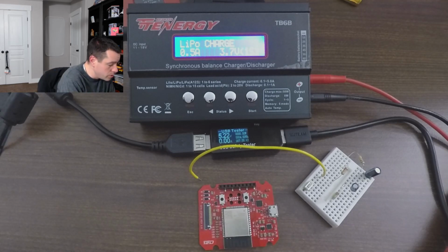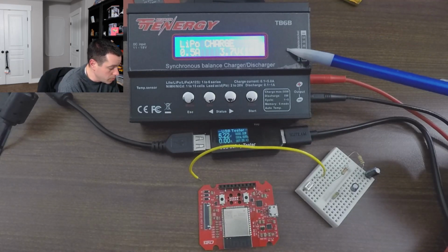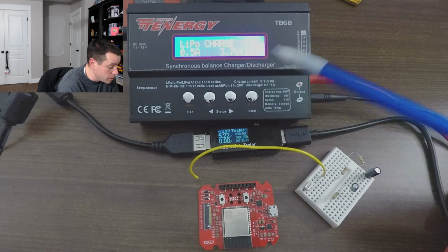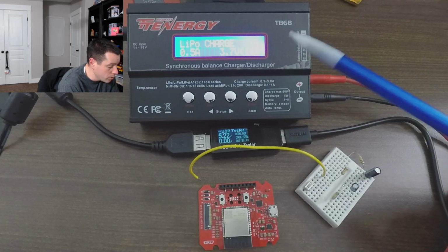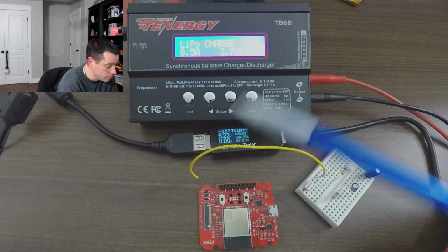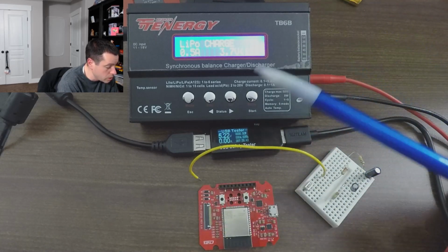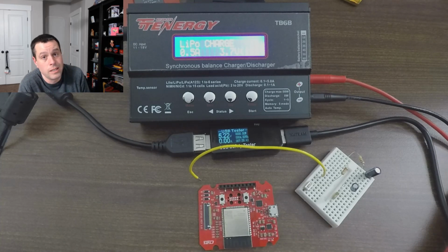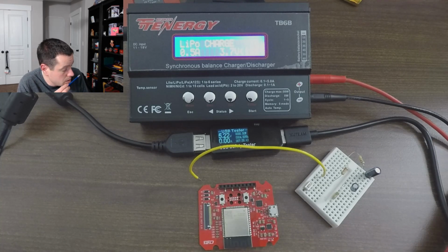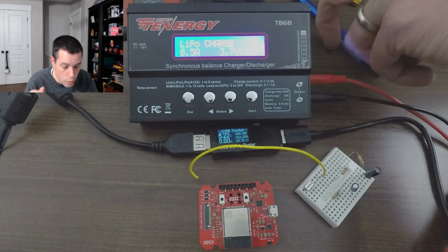But anyway, I can use this to put a battery in different voltages very quickly. I can put one at 4.2 volts, one at 4.1, one at 4, 3.9, 3.7, 3.8, 3.87654, all the way down to discharged, and then just plug them in one at a time and see what the ADC says as it's reading that. And that's a simple way to test that. And if we could do that, great.